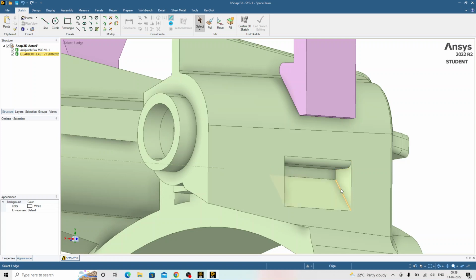In other words, the finite element analysis software has to capture all those geometries to build a mathematical model. Since those fillets do not have any significance, we don't want to spend time on capturing those fillets using the elements.